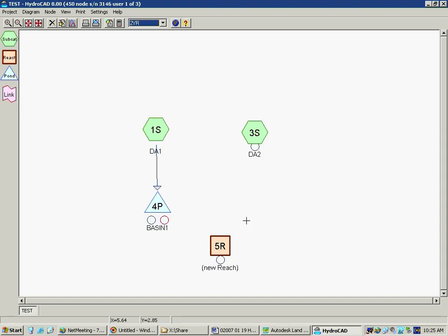Sort of a point of interest almost. Your study point, decision point, point of interest, whatever you choose to call it. It can also be used as a channel to add time or to account for flow down a watershed. One caveat, if you use it as a channel, it's entirely possible to have channels within your drainage area that